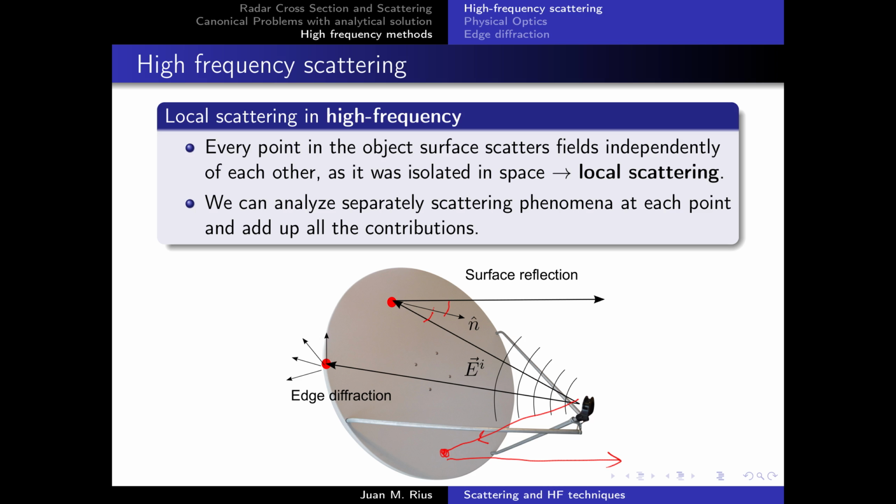You know that in numerical methods, the discretization of electric or magnetic field integral equations leads to a linear system, because you set the boundary condition for the total field at different points in the scattered surface, and the field at a given point depends on the field radiated by equivalent currents at all points of the object surface.